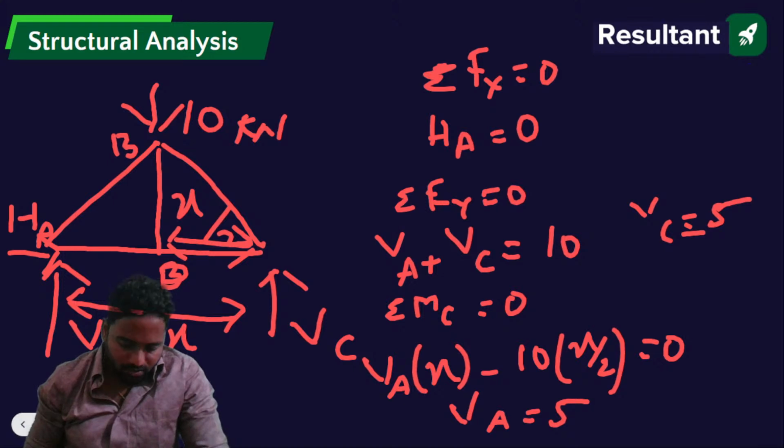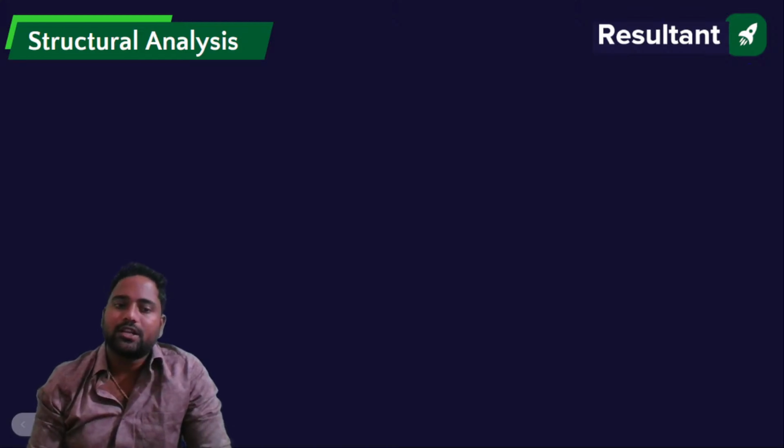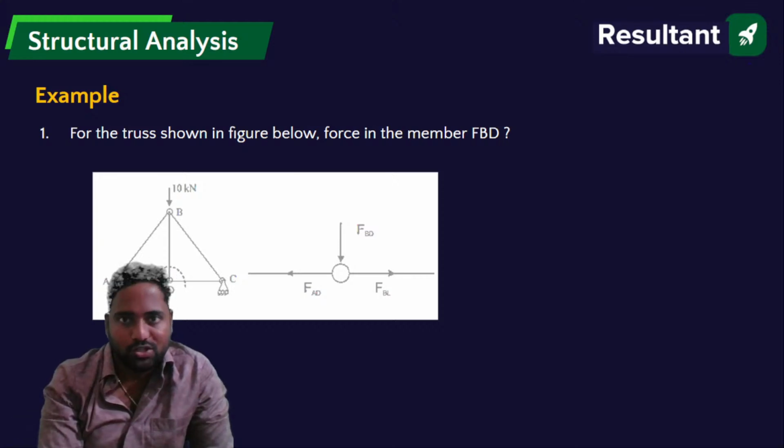So once you find out the reactions, what is the next step? Now you have to consider the equilibrium of the joints.